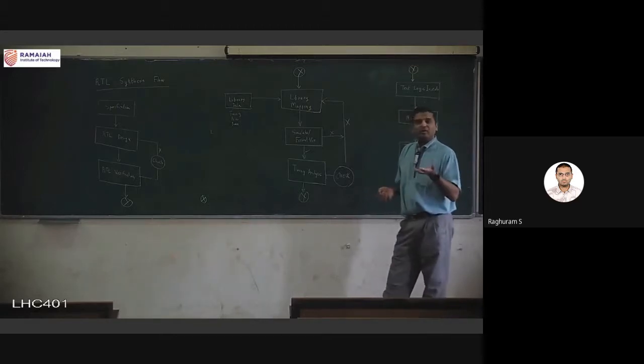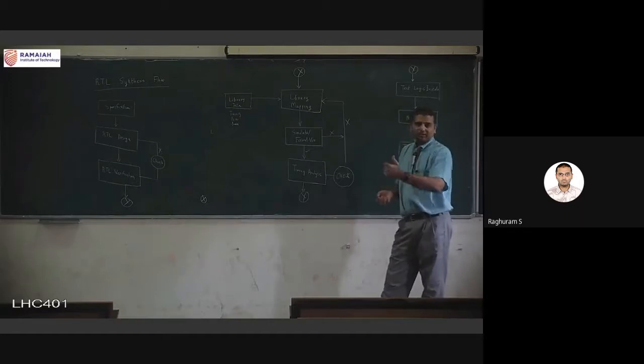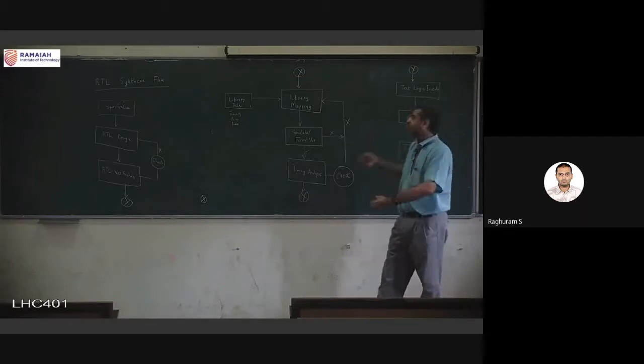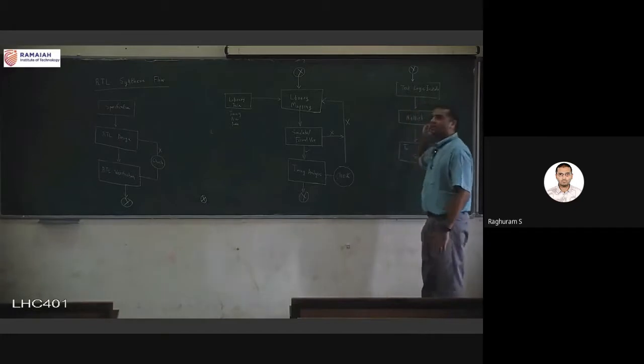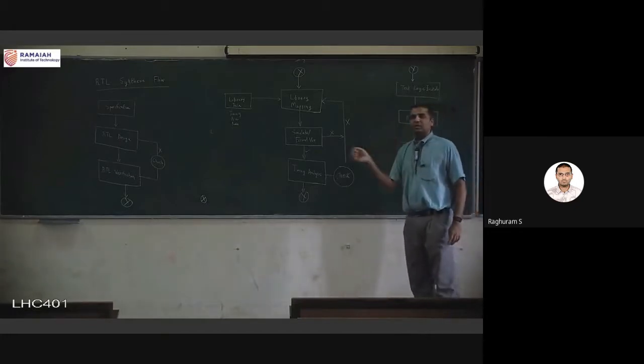How do I check that? I can give some input. I know what output to expect because I know the gate functionality, but I should be able to give that input, and I do that through the test logic. And test logic, generally, like I said, has a test mode and a normal mode.